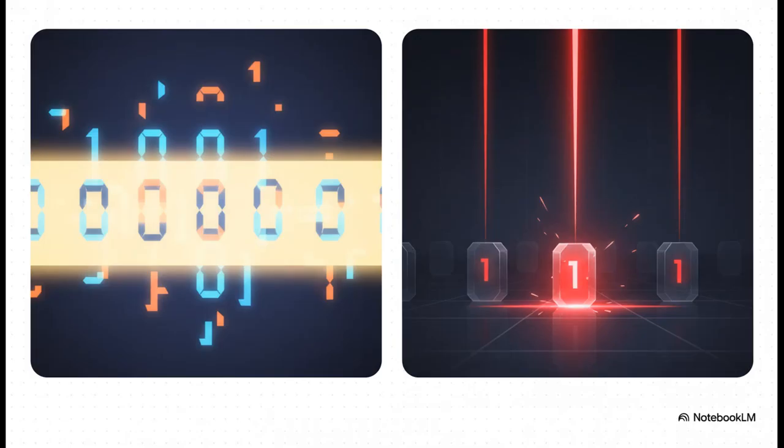Okay, so this is probably the most important difference to get. A latch is level sensitive. That means it's listening for changes the entire time the clock signal is on. That long window of time can lead to all sorts of weird, unpredictable behavior. A flip-flop, on the other hand, is edge-triggered. It's so much more precise.